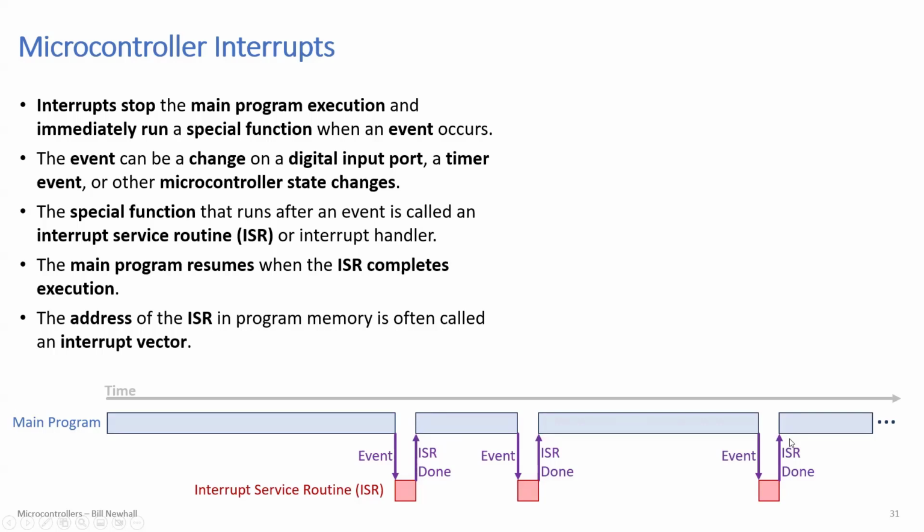Okay, so you could do things like capture timer values. In your code in lab, every time the blade crosses the infrared sensor, an interrupt happens and some light calculations are done to calculate the RPM. So these interrupts are useful for storing timing of events.